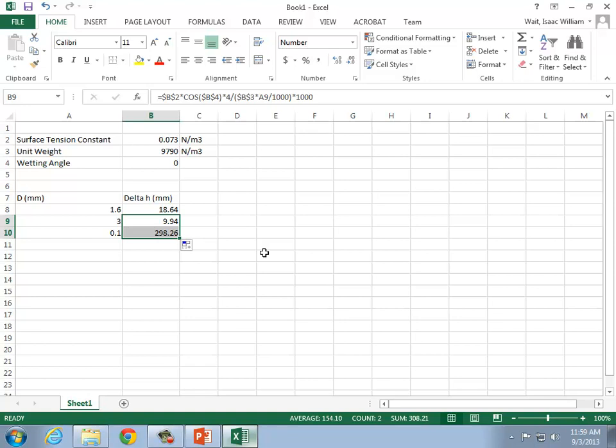Now above the water table, it's not that there isn't any water, it's just that some of these voids, as they're called, can be full of water, can be full of air, or can be partly coated with water. There can be a layer of water wetting the soil grain, because remember what we said is that water is attracted to SiO2. Well, SiO2, glass, is made out of melted sand. And so soil grains have SiO2, and so there is an attractive relationship between the water that's in soil and the soil grains themselves.